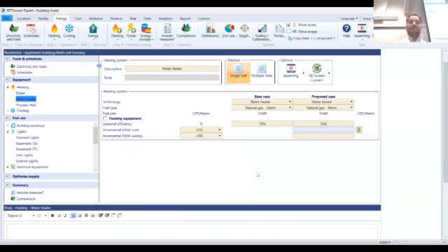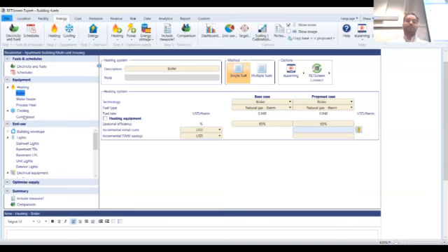Next, there is a water heater in the building that has a seasonal efficiency of 70%. Process heat has a seasonal efficiency of 100%. You can select the source of fuel as well. If it is an electric boiler, you can change the source to electricity and accordingly define the fuel source. Next, we go into the cooling load.